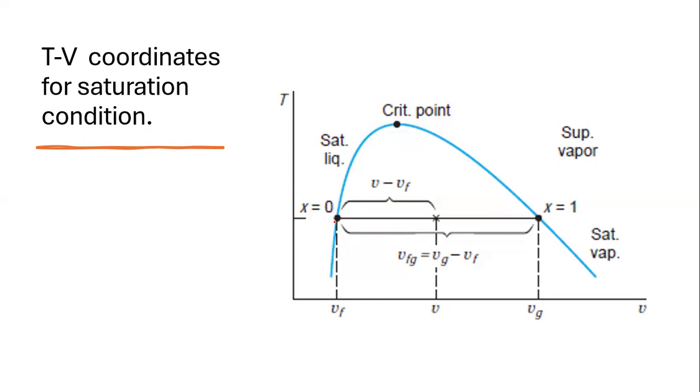Now remember, there is that line over here, and this is the isobar, say our pressure here is 0.1 megapascal, right? This is the same as what we looked at. Remember, I said to you here we have the saturated liquid, and then here we have the saturated vapor. I'll explain the V later on. Here we have the saturated liquid. So what does that mean? Saturated is a mixture of liquid and vapor.